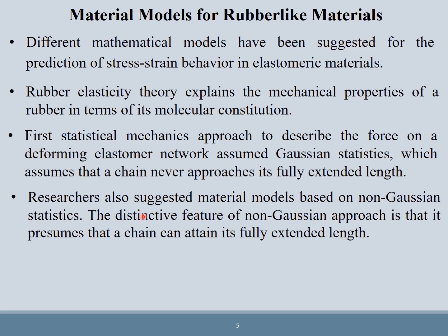The distinctive feature of the non-Gaussian approach is that it presumes a chain can attain its fully extended length. So that is the difference: in Gaussian, the chain will not reach the maximum stretchability, but in non-Gaussian, the chain can reach the maximum extensibility, or the maximum stretch.